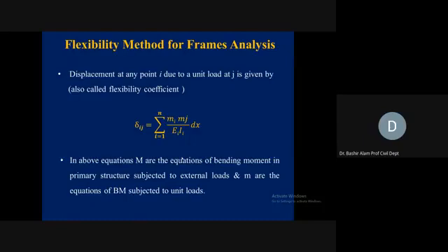In the above equation, M are the equations of bending moment in primary structures subjected to external loads, and small m are the equations of bending moment subjected to unit loads. So here you can see the definition of the m's.